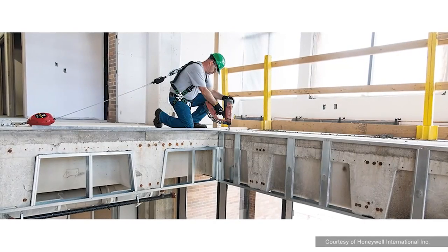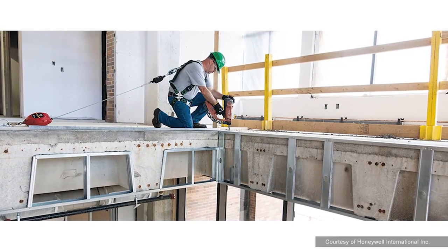Leading edge we would define as any place where, when a worker's tied off with a fall arrest system and they take a fall, their lifeline, whether that's a rope lifeline, a cable lifeline, or their lanyards, could strike that edge, and the anchor point is going to be on one side of the edge and the worker is going to be on the other side of that edge.